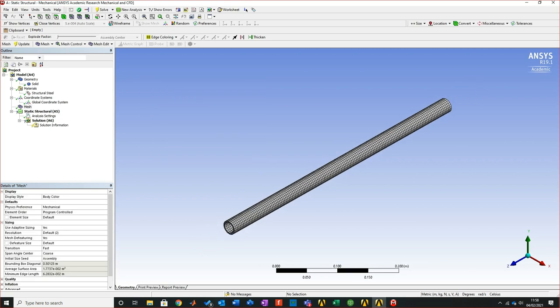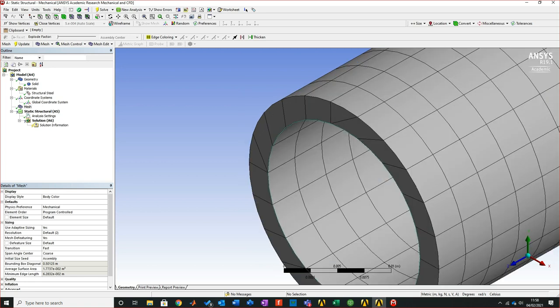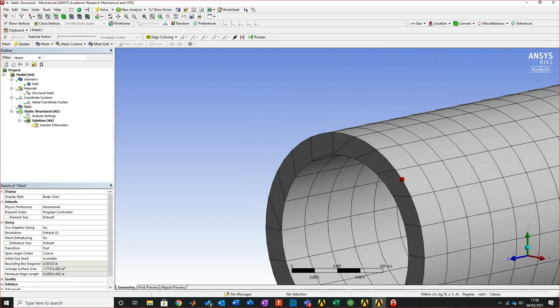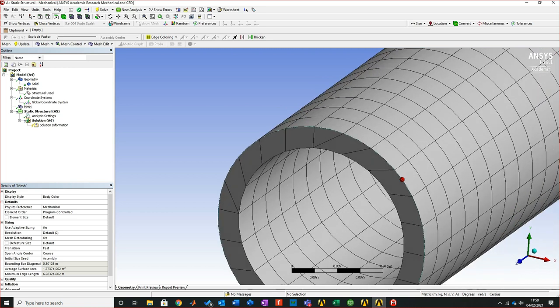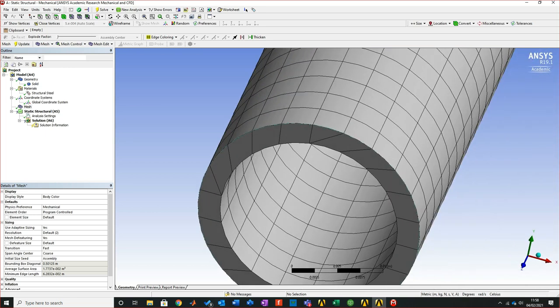So what it's actually done is it's used a combination of tetrahedron and quadrilateral type mesh. Now you notice here it's in a brick fashion. This type of mesh is exactly the type of mesh that it needs to be, if you think about it. Now when we bend this, it's going to deflect around Y, and we want that stress to concentrate. Now, often what can be brought in can be a triangular type design.